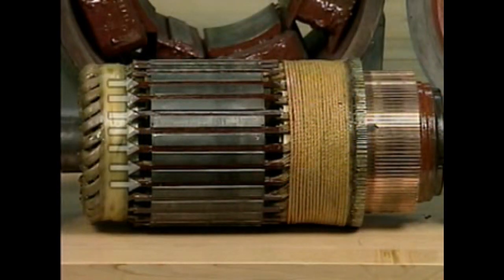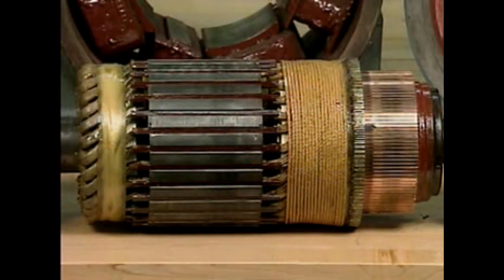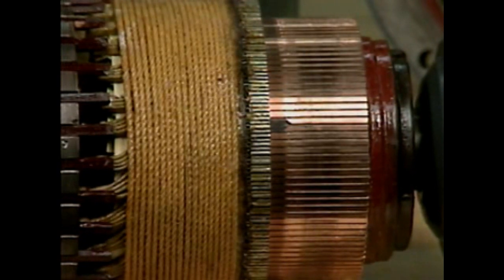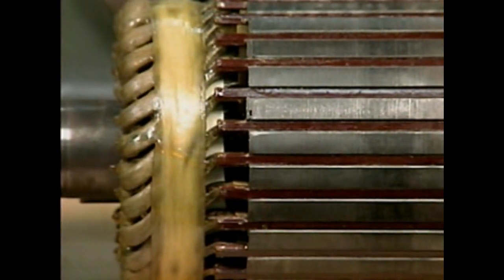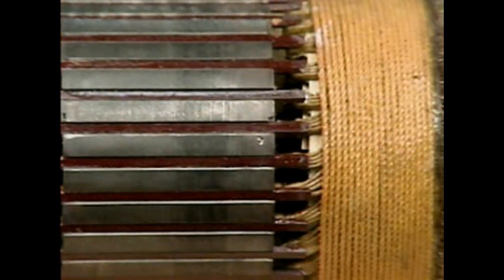The armature contains several loops of wire that are wound back and forth. All of the loops make an electrical connection to the motor's commutator segments. The electrical connections to the commutator segments are protected and held in place under a wrapping of varnish-coated fibers. Current flows from one commutator segment through the armature and back through another commutator segment.